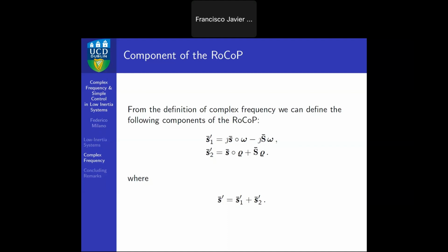So maybe the imaginary part of S1 that depends on omega may be super small, but we control it, we can make it as we want. So the message here is that in practice, and this is probably known anyway, there is always, even if it's weak, a link between Q and theta and P and V. Here we are saying that there is a link between the derivative of P and omega and the derivative of Q and omega and so on.